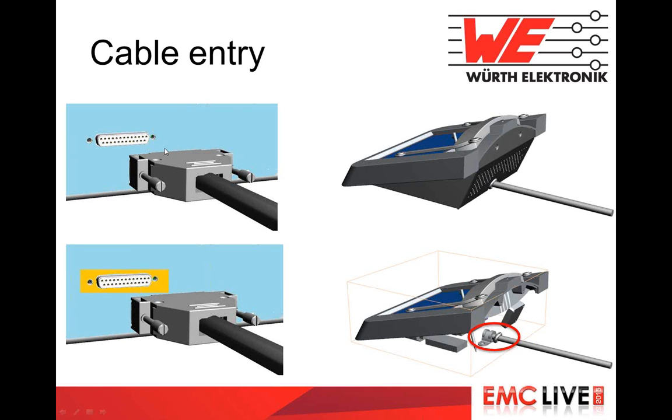For the connector, we have to assure that we are connecting 360 degrees around the connection. As we saw before, it can look like we are making a perfect connection, a D-sub connector for example, but if we look carefully, we probably have contact only in the screws and maybe in the corners. So we still have some discontinuities. We have to think of the shield of the cable and the shield of our device as part of the same shield, completely connected without leaving any aperture. Here, conductive foams or gaskets stamped with the proper dimensions will help us, as with the seams and the joints, to have a perfect connection all around.